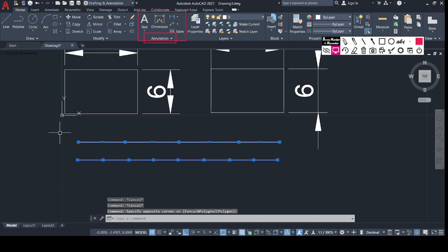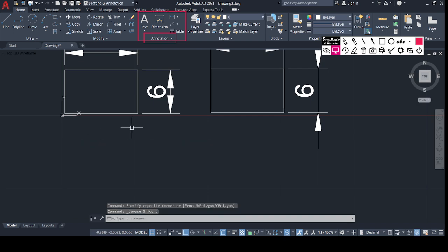Understand? So these are the first difference between line and POLYLINE. And the other difference is, if I click the POLYLINE command and click on a first start point, now you can see there are lots of options: arc, half width, length, width. So in POLYLINE there are lots of commands we can use inside the POLYLINE.